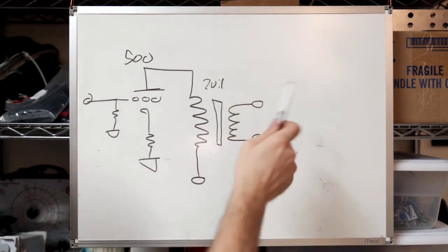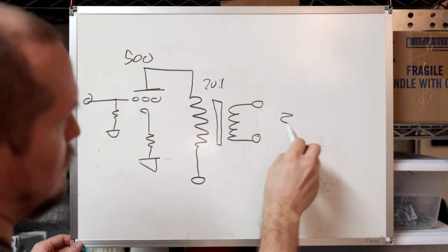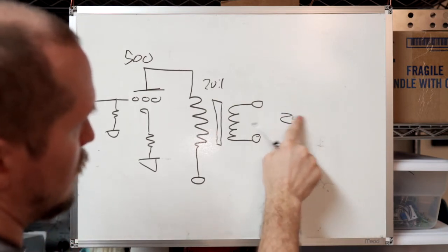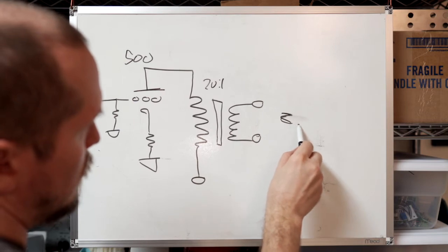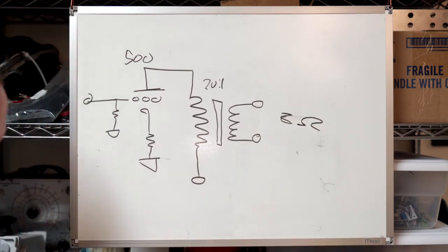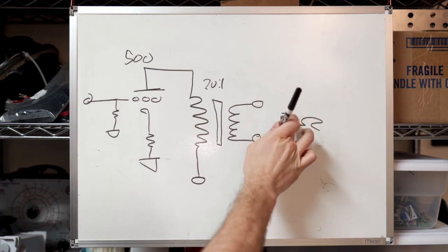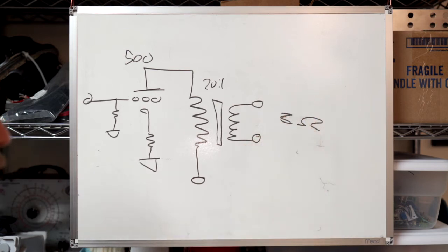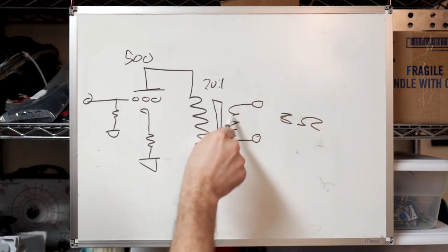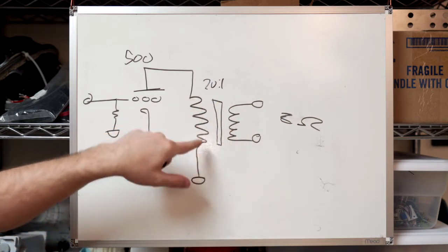And so the output impedance of your amp is going to be something like 2 ohms or something like that. 2 ohms, like that. And so that's much more than the solid state amplifier's example. Now also you add to this, the 2 ohms right here, it wouldn't actually be 2 ohms if you measure it, because you have to add to that the DCRs of the windings as well.